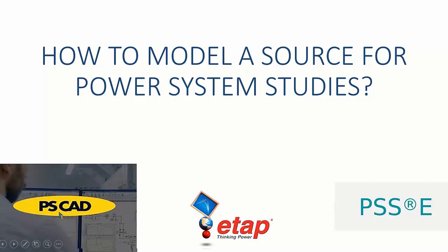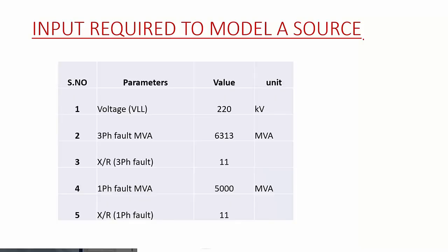In this video, let me tell you how to model a source for power system studies. To model a source, we need to collect certain input data from the customer: the source voltage, 3-phase fault MVA and single-phase fault MVA of the source, and its X/R ratio. In fact, both the 3-phase fault and single-phase fault.